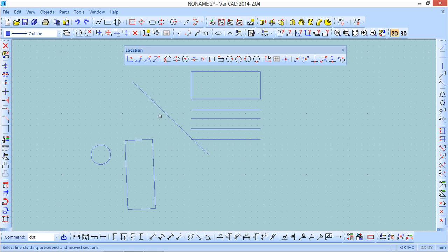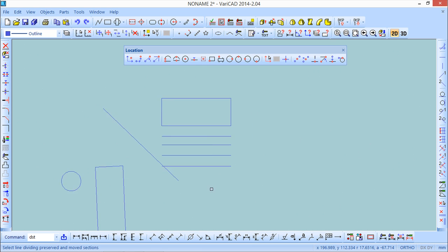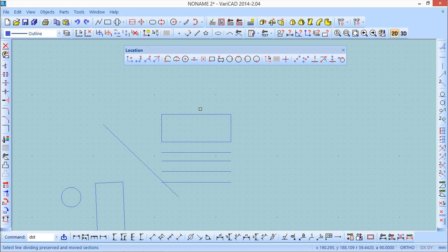You must notice that this is something that will make a stretch along a defined direction, or it's the same to say by 2 points. It can be done only on lines because the other objects, if present in the choice, will be just moved, not stretched. So we'll try to make it on this rectangle here, even though the result in this case of the horizontal stretch will be quite similar to the option inside the menu.